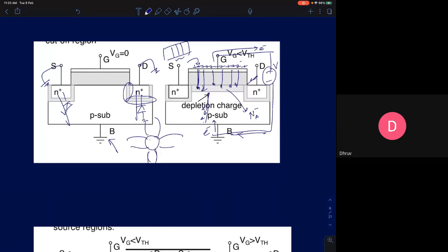If you replace one of those silicon atoms with a boron atom, it's going to have one hole, one vacancy. Now the electron which goes to the surface will fill that vacancy. Once it fills that vacancy, boron acquires one extra electron, and it becomes a negatively charged ion.